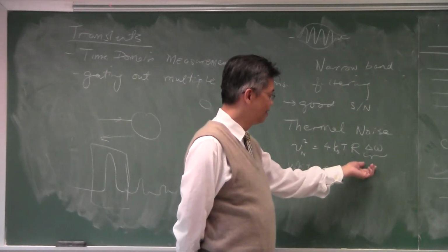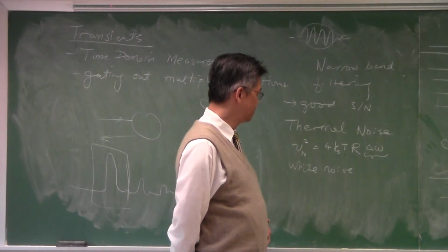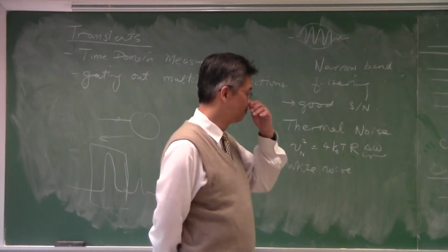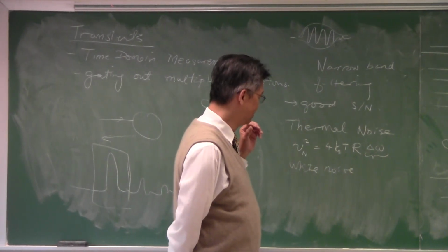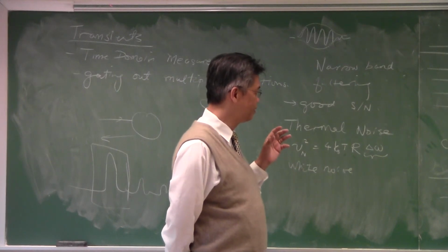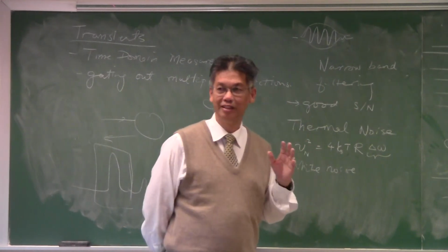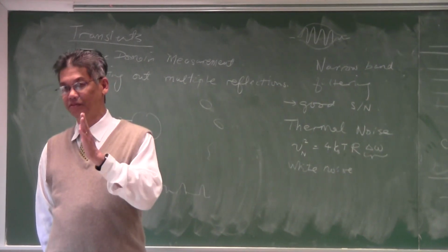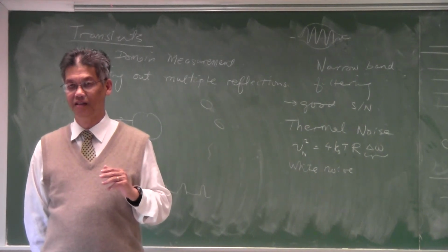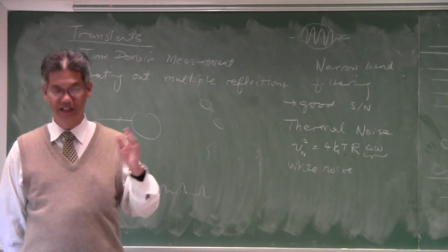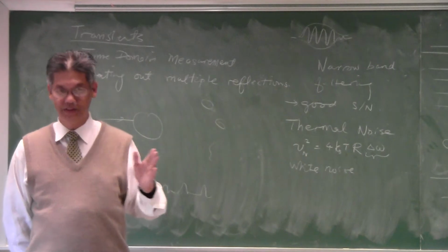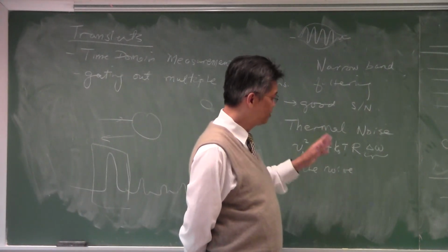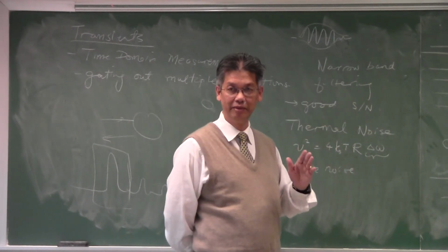And then if you do that, the noise that comes through your system becomes very small. Okay, but if it becomes very small and it's very narrowband, what does it mean? It means that you have to actually measure a system over a long time scale. If it's a kilohertz signal, that means you measure over a long time scale, you do time averaging, or multi-shot averaging, or averaging over many duty cycles.